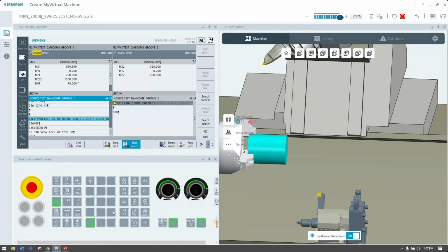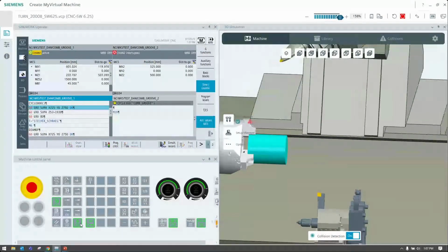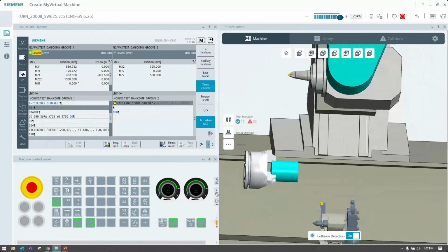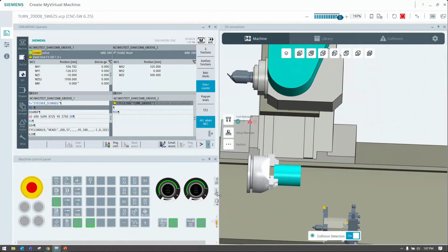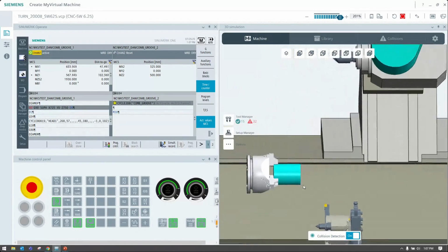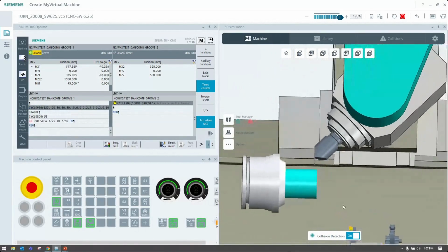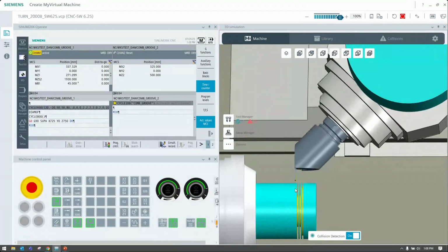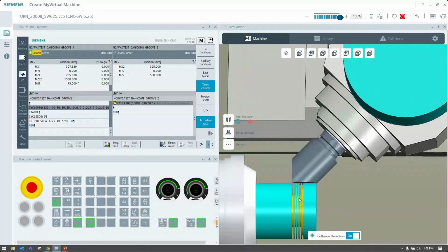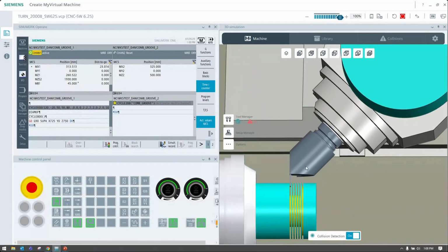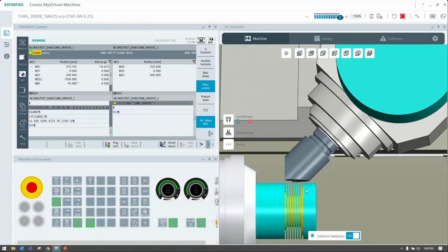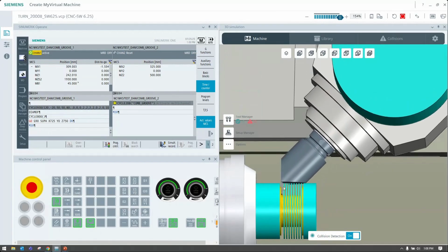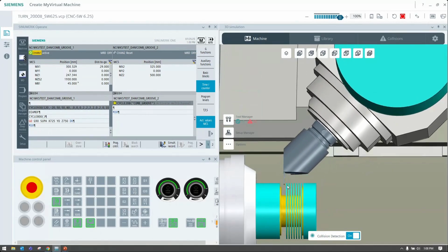If we execute this, you actually see why it's called comb grooving and why it gives you a much more increased cycle time. We got our groove tool coming out. We're going to orient and start to groove here. Why it's called that is, when we see our shape here, it's going to look like a comb. The nice thing is we're taking full width of cut, and we're not alternating back and forth. Because of that, we're staying in cut longer. Now we're just going to go by and break down all our individual comb pieces that we've created here.